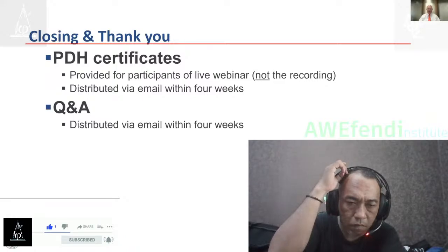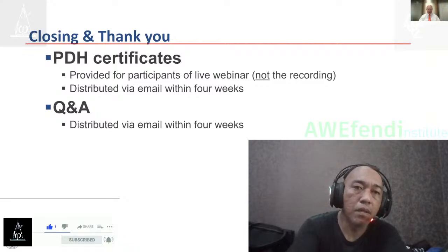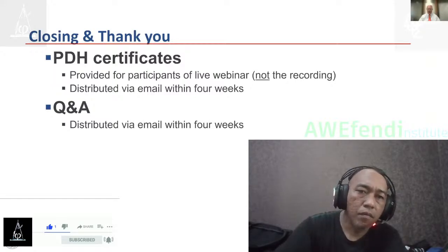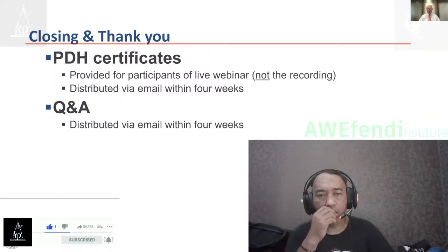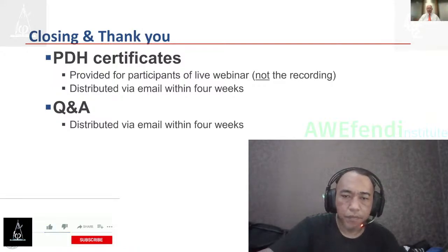And there were concerns about irregularities. They were quantified, there were graphics drawn, there was voting on it. And at some point, when that was translated into the NEHRP recommended provisions, some adjustments were made, and we think there was not a good reason to make those adjustments. So we as our project looked at it, and then also the ASCE 7 Seismic Committee readdressed the issue. And the dimensions that are in ASCE 7-22 are more consistent with what we anticipated when first formulating these irregularities 40 years ago.